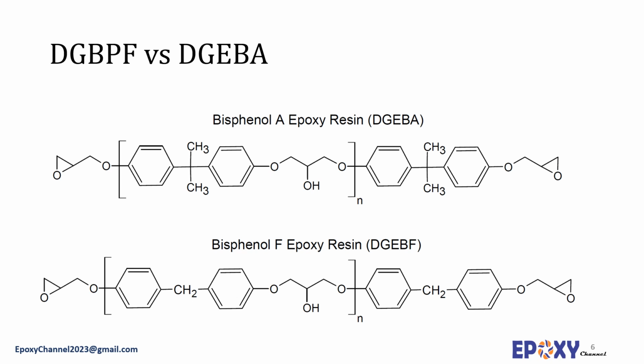Crystallization is often a problem with liquid bisphenol A resins, and this can be reduced with bisphenol F resins. In terms of crystallization tendency, it should be noted that bisphenol F resins perform very well. Compared to diglycidyl ether bisphenol A, the Bis-F component has a lower tendency for crystallization and can be used for applications where crystallization might be an issue.